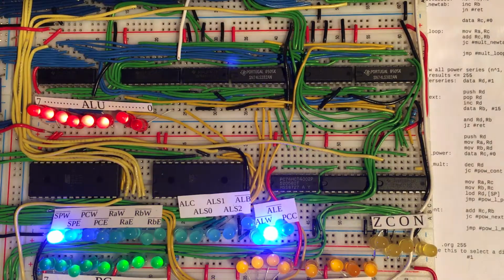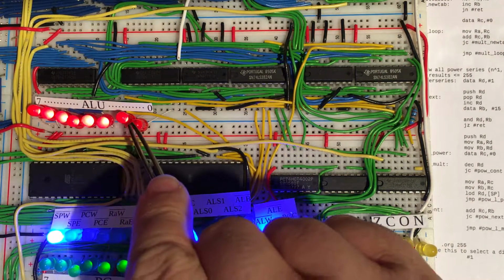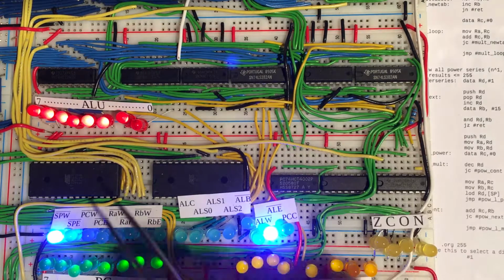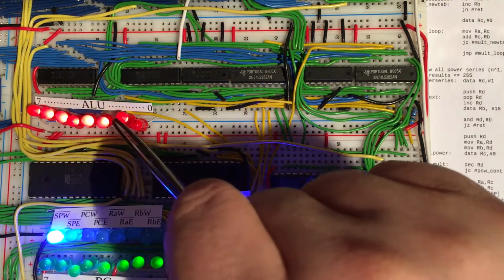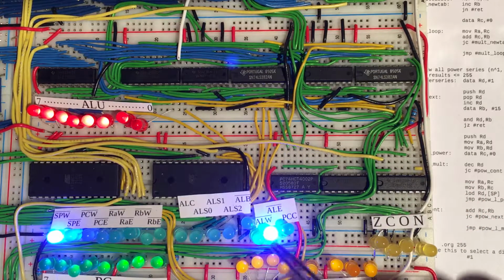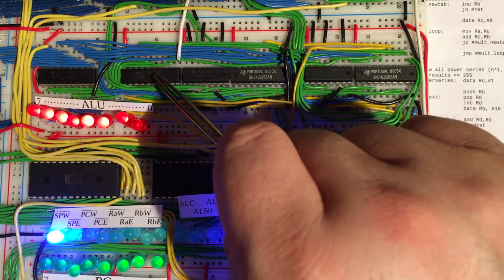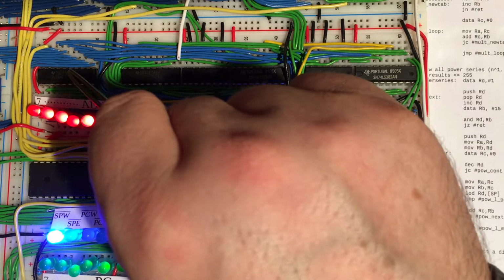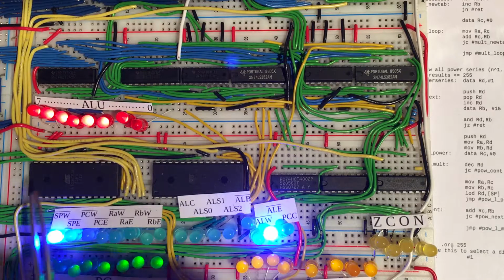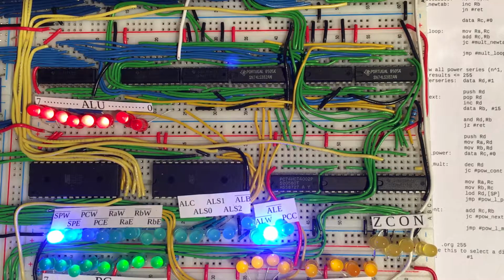So if I advance the clock, then there we have 254, and so that was one example of an ALU operation. But as we saw, we actually need 2 cycles, because that value is now inside this register, and only now are we able to write this 254 out onto the bus. And we're doing that using this ALU enable signal. So the output of that register is now going through this buffer chip which has been enabled onto the bus, and so the stack pointer will actually take the result of that calculation and latch it inside the actual stack pointer register. And there it is.